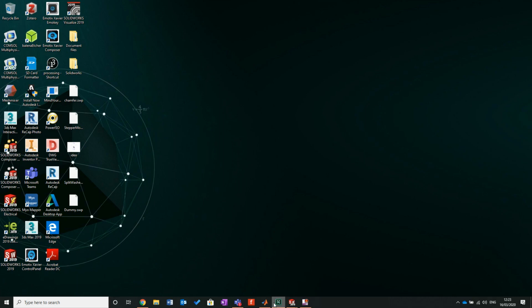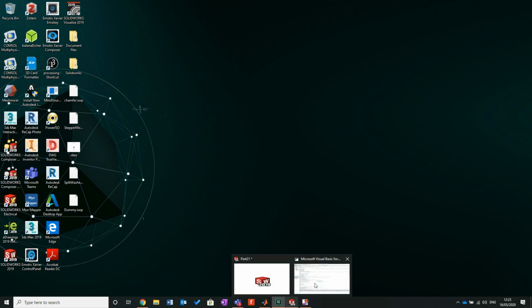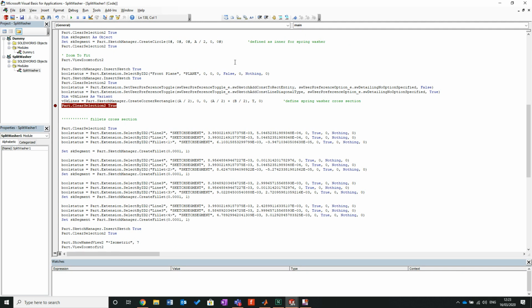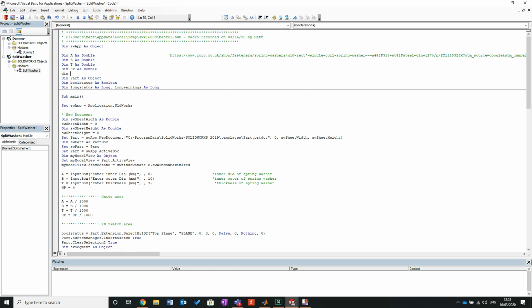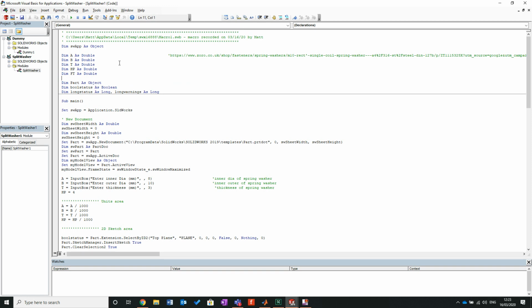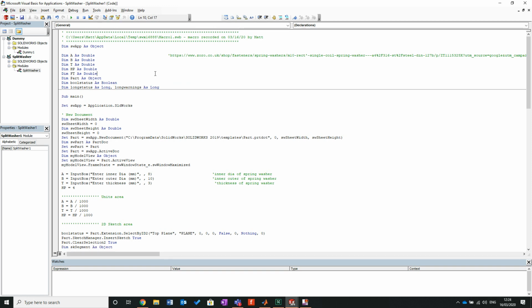So if I come back onto my fillets, let's scroll down to fillets. Bring that into there. And we have our fillets at 1 millimeter. I'd like to have that on control. So I'm going to go dim, fill, as, call it FT, as a double. Again, promoting that control. I can control everything.